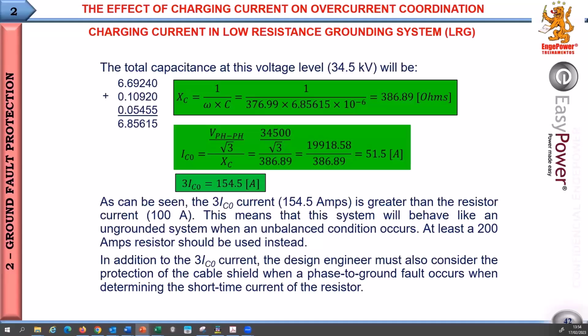And this was proven by the digital fault recorders we had, and due to the events that happened, the main warning for us is that when you have a ground fault in a specific location and simultaneously you have other ground faults in other locations, this is a warning for us that our systems are not behaving as a grounded system. Okay? Good.